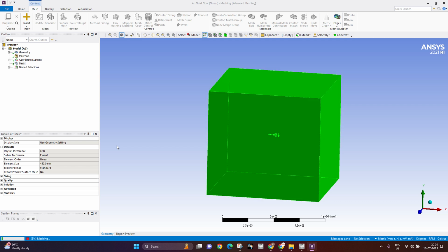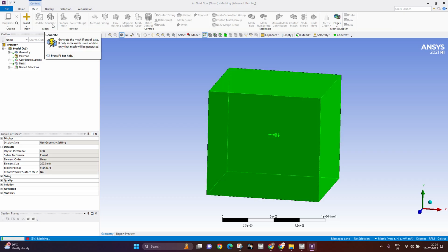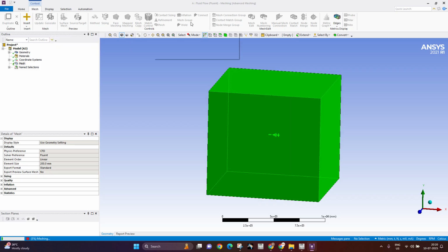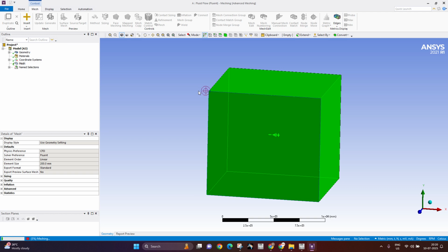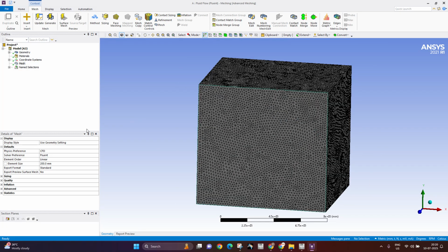The lesser the cell size, the more accuracy. I will decrease it a bit more. I'll assume it is 400. 400 divided by 2 is 200. I can actually give it 225, but still, I'll just make sure it is simple. So I guess 200 mm is enough. It will take a lot of time. So this is actually enough. You can decrease a bit more.